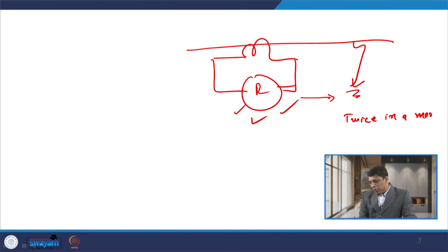So, when we carry out periodic testing of the relay, what do we have to do? We have to remove the relay from the case, from the panel, and then give some external current injection through a current injection test kit to the relay, and check whether the relay disc, if it is electromechanical type, or a static or digital relay, operates within the specific time period as given by the manufacturer or not.